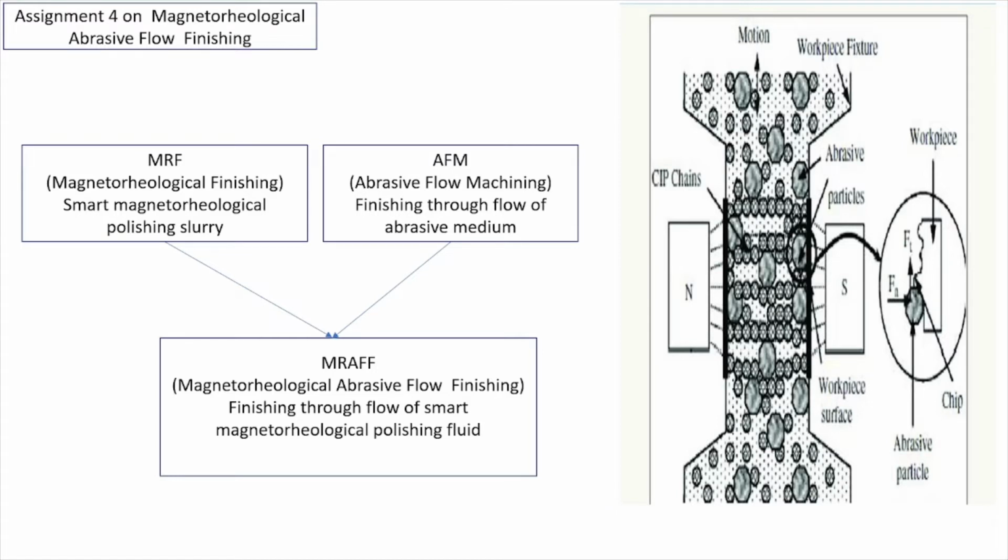Basically, the magnetorheological abrasive flow finishing process, or MRAFF process, provides better control over the rheological properties, like viscosity and shear stress, of the abrasives in the finishing medium.